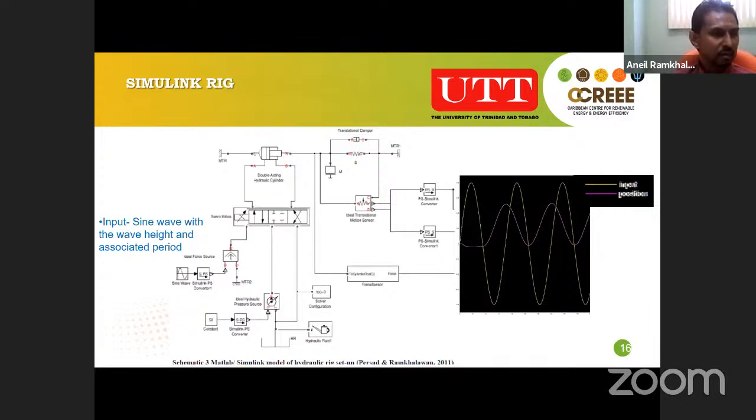We were looking at the high forces we can get from a hydraulic system, and the speed and ease of control for an incompressible fluid. So let's say oil versus a pneumatic system, where air is compressible and you'll have difficulty in controlling the motion.